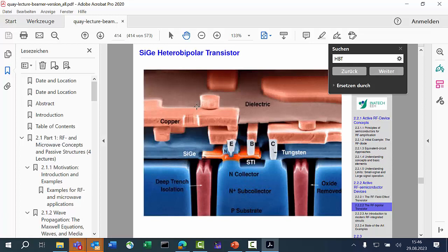And here you see also, maybe this is interesting, the impact of the parasitics. So here we have such a transistor, and you see the transistor is very small, but we also have the surroundings, and you see they are very large. And all the metals are very broad to have very low resistance, very good conductivity. So we take copper to get the best connection.